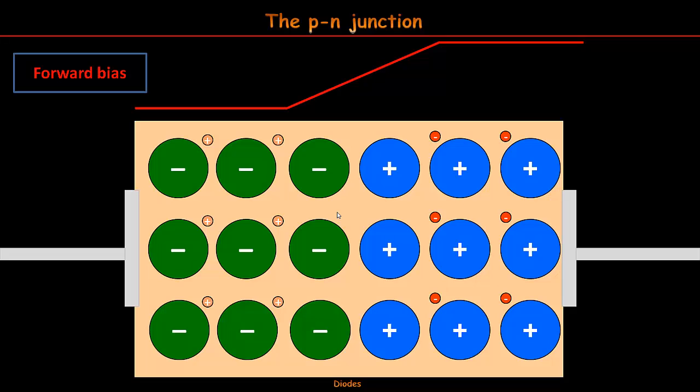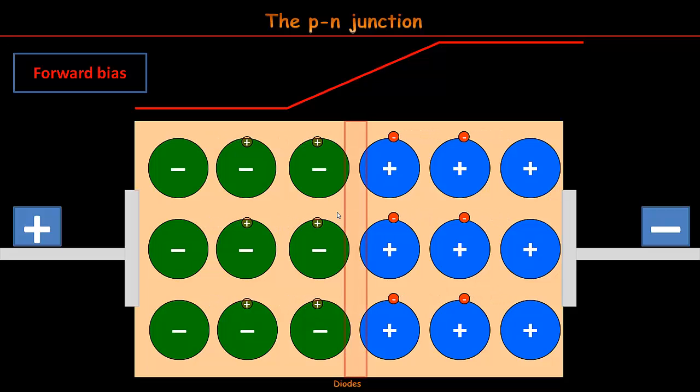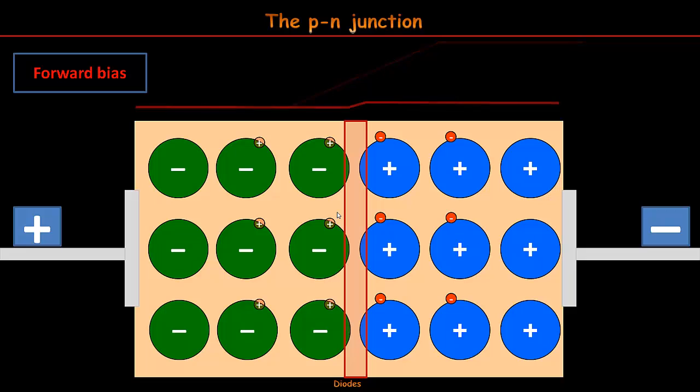With a positive voltage between the P and N sides, we get a double effect. Think of it with charges. They are repelled by the applied voltage, so they tend to get closer to the junction, no matter if they are positive or negative. Negative charges are repelled by the negative voltage. The same with positive charges and voltages. The physical effect: the depletion zone is now thinner. Regarding voltage, the barrier has been removed. Electrons can cross it easily.